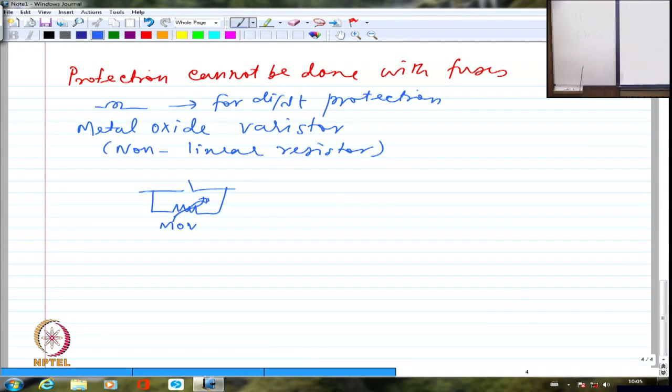As long as I'm applying only 2 kilovolts, it will be able to withstand that. That's not a problem. But if by chance a voltage greater than 2 kilovolts comes across this, it will break down. So essentially a huge current will go through it, and the overall voltage across the MOSFET also becomes very small. So the MOSFET will not get spoiled.